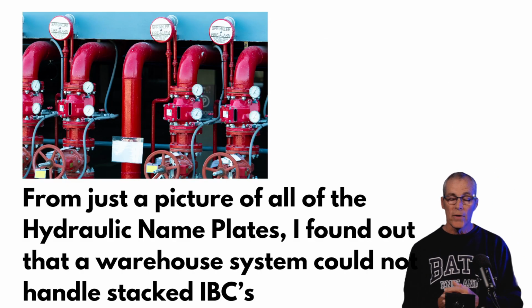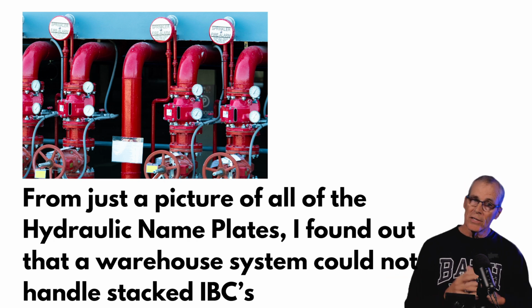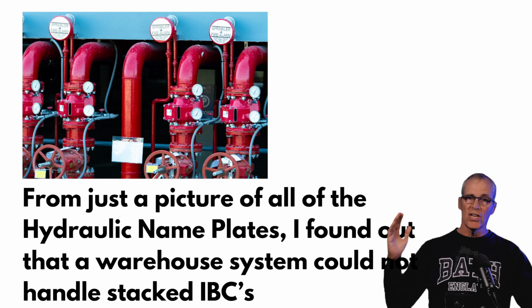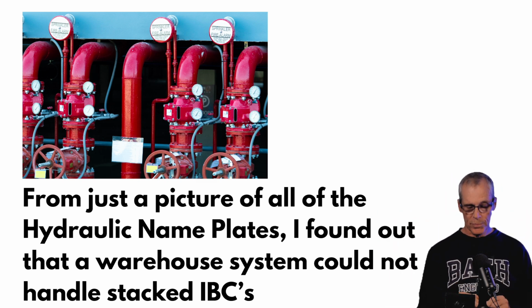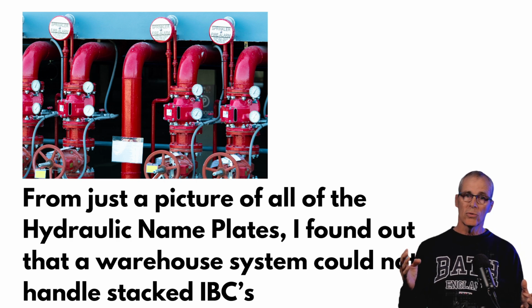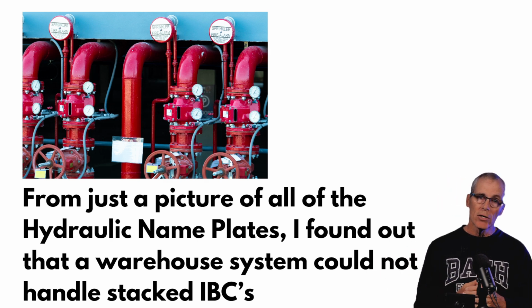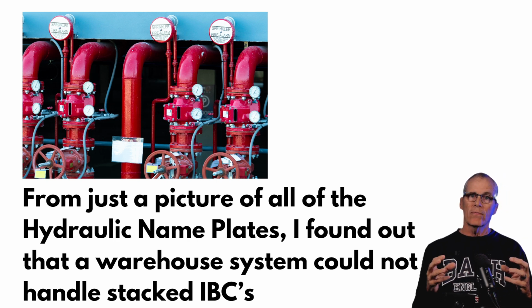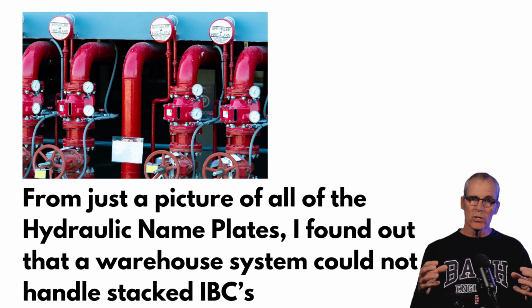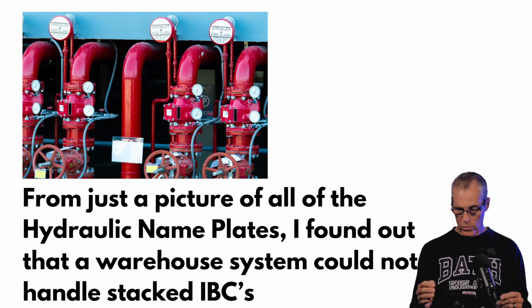I couldn't believe an engineer submitted, this was an insurance company engineer. This is not the picture they submitted, but they had a picture of several hydraulic nameplates, like the little square picture in the middle of this picture. On a hydraulic nameplate, it tells you what the system design is, so what the concentration of water needs to be, flow rates, pressures, and it tells you what area it's designed for. So it gives you an idea of basically how much water this system's going to put out. Well, I took a picture of that. And I didn't need to take a picture of the IBCs, but I also took pictures of the IBCs.